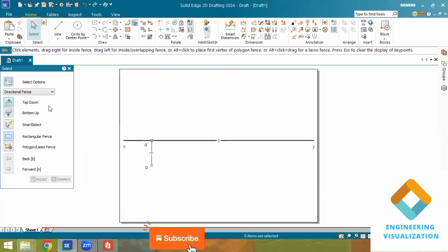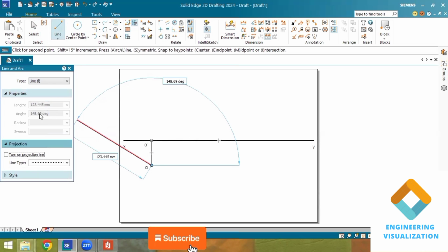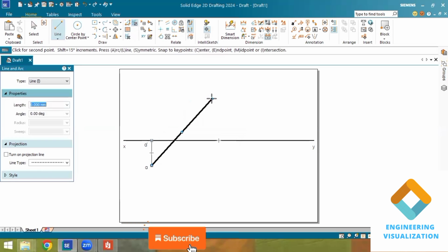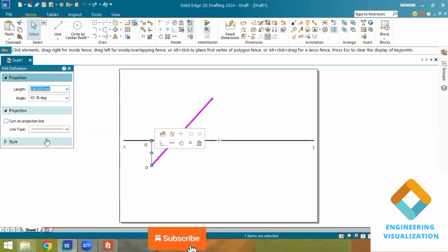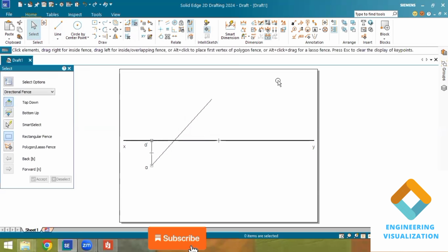So what I'll do is connect the top views at an angle of 45 degrees. From the top view I'll draw an angled line. Here we can just draw it randomly, and then change the angle. First I'm drawing one line. You can change the thickness. Select the line and select its thickness as 0.13. Now I'll change the angle.